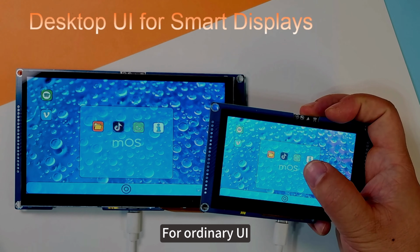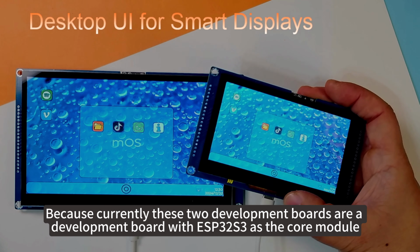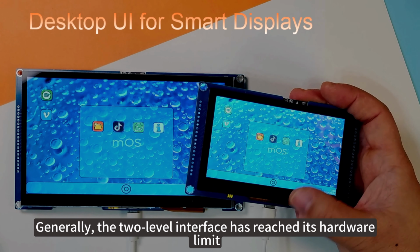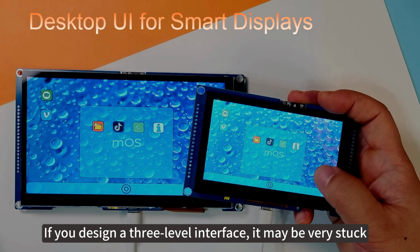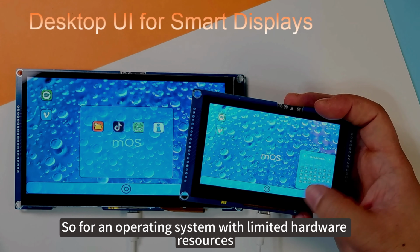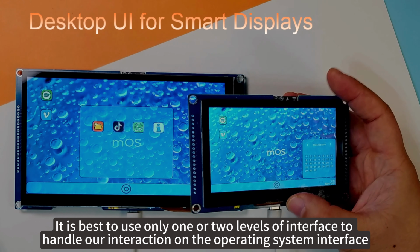For ordinary UI, generally, we only need the first level UI. Because currently these two development boards are a development board with the ESP32-S3 as the core module. Its own resources are relatively limited. Generally, the two-level interface has reached its hardware limit. If you design a three-level interface, it may be very stuck. So for an operating system with limited hardware resources, it is best to use only one or two levels of interfaces to handle our interactions on the operating system interface.